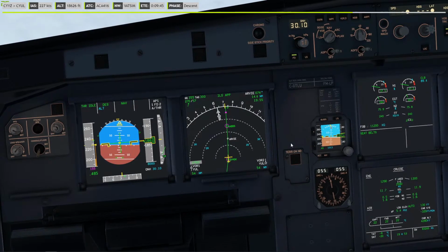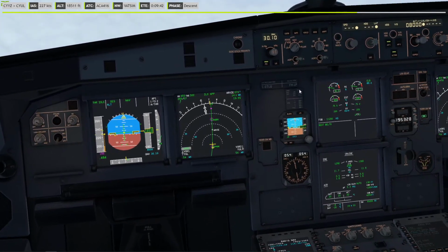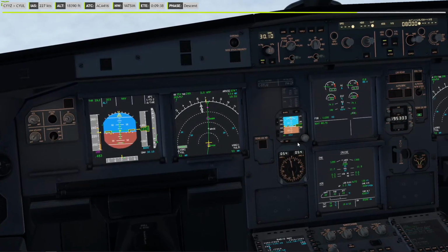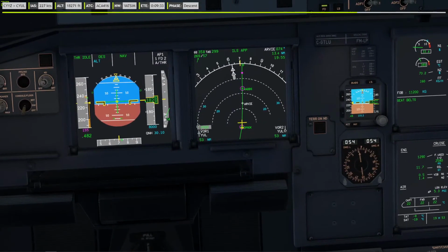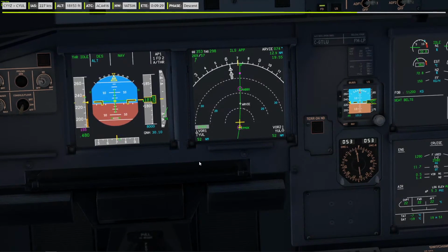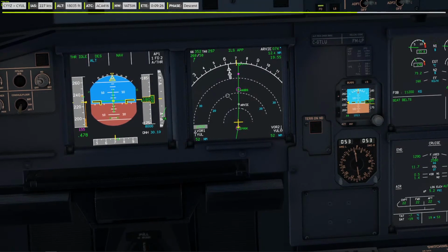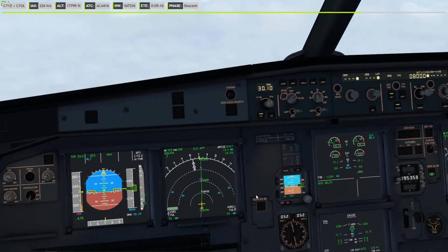So we just set the altimeter to 3010. The restriction is supposed to be passed at 15,000, so just confirm that. 18,000, coming up to 15. Yep, that should be fine. Our profile, just on it, 3016. I've set 3010. I'll keep it at that.